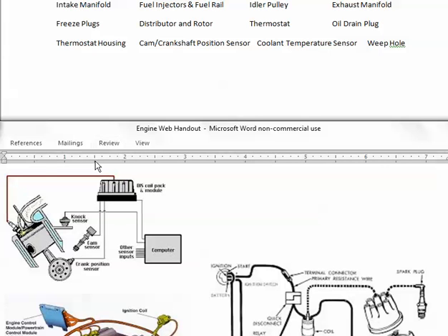Obviously, we will spray in fuel first, and then on the next stroke after intake, after combustion, we will have your spark. So intake, we'll spray in the fuel using the crank or camshaft position sensor, or the combination of the two. Spray in fuel, compress it, and then because we know the position of it on the second stroke after that, we will ignite it.